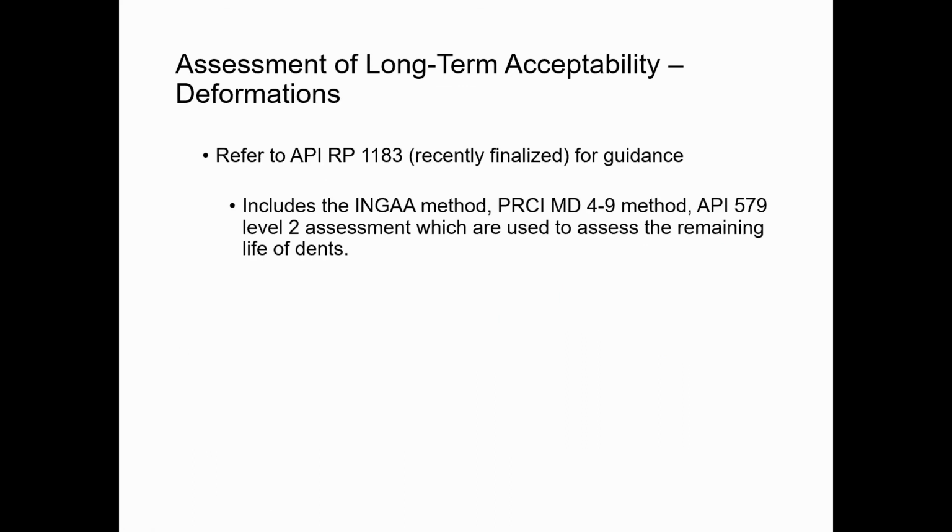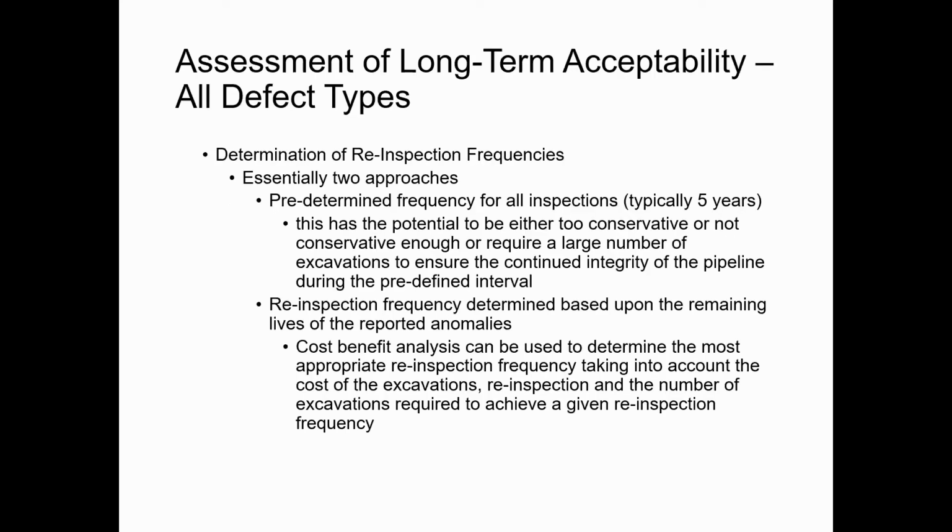With regards to determining the long-term acceptability of deformation anomalies, the recently finalized API Recommended Practice 1183 provides guidance on this. It incorporates research that was done by INGAA, the PRCI MD4-9 method, and guidance that's provided in API 579.